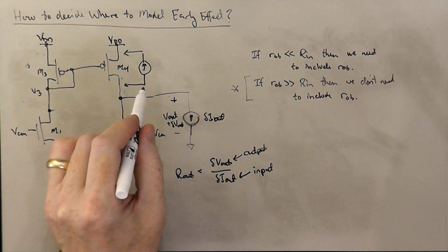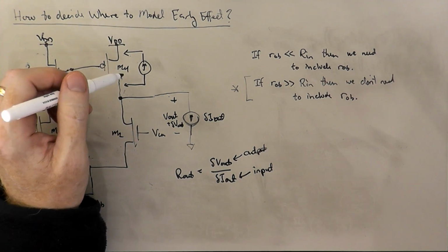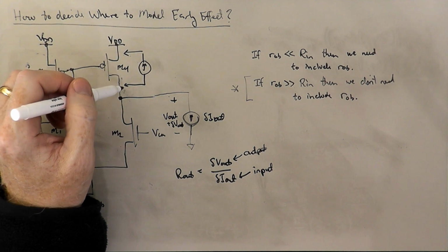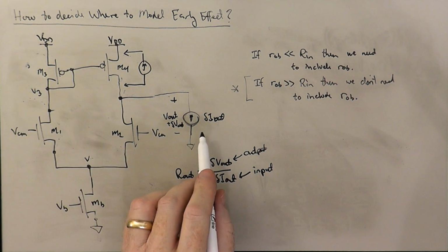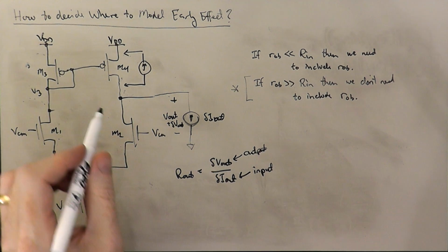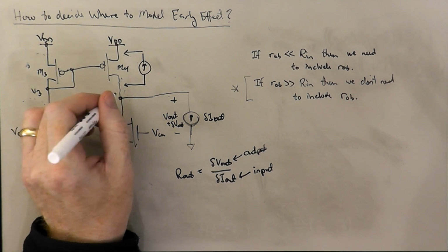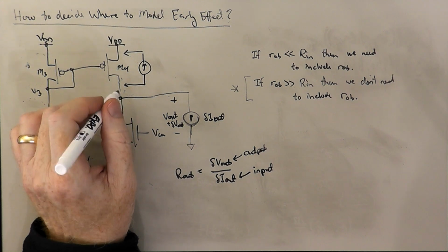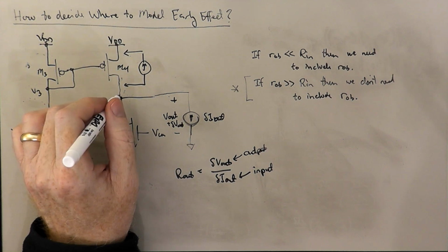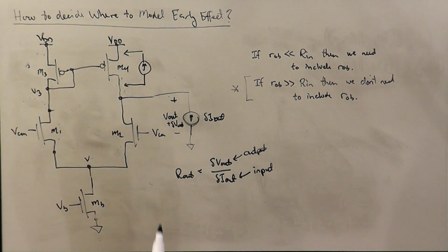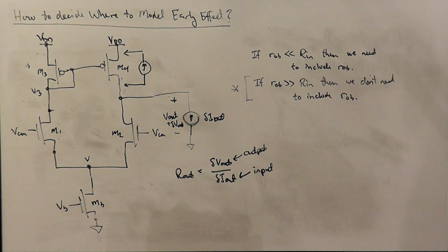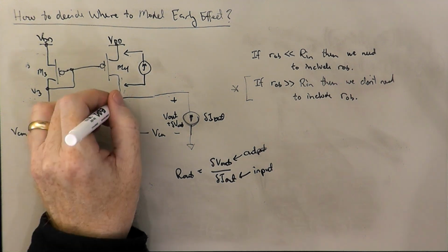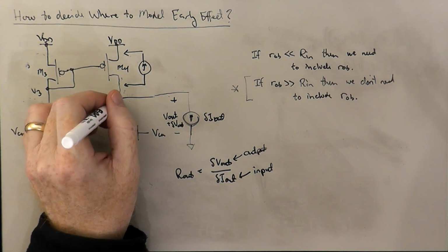But when I suck current out of the drain side, now all of a sudden, I'm pulling current out of a pair of drains of ideal transistors that are not being held fixed by the voltage source. And so for non-zero delta I, I would get a very large movement of voltage here. I don't get something that's proportional to delta I. And so I would have an infinite incremental impedance here.